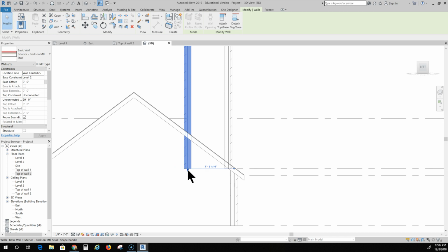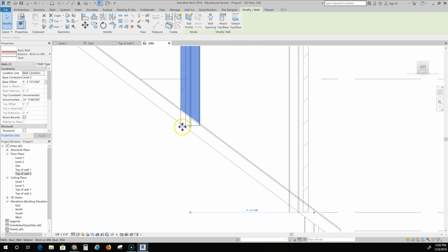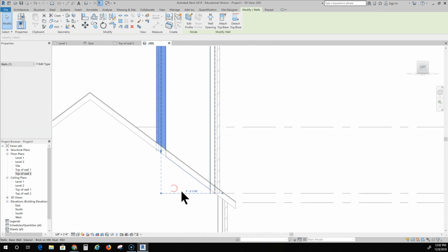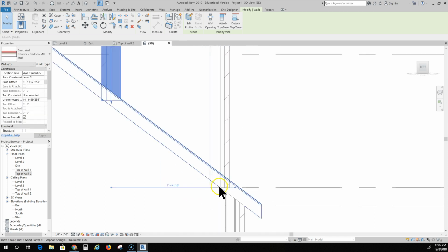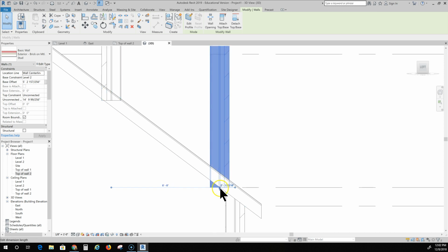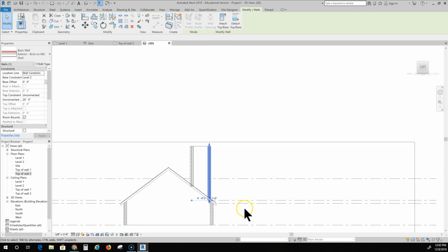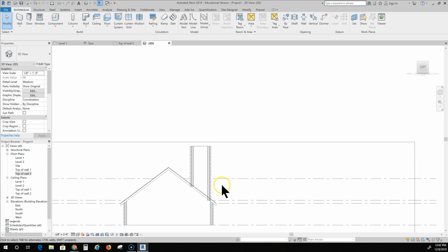Now I can edit this wall, the back wall, which I can just do from here. Move it straight up, get it right in there. And of course you see it does stick down just a little bit, but they can fix that in construction. And same here, this one sticks down just a little bit. And I don't really want it to, but they can fix that in construction. I don't know if I can move it up because I did not. Yeah, it'll just have to stay there. All right, so now I have adjusted all of my walls. Now, if your dormer is back a little bit more, then this front wall will protrude into the living space a little bit. So you would actually have to adjust that one as well to make sure that it does not do that.